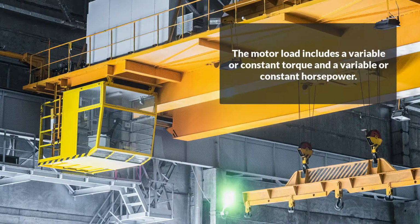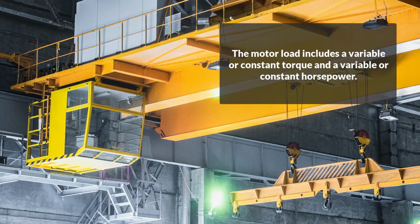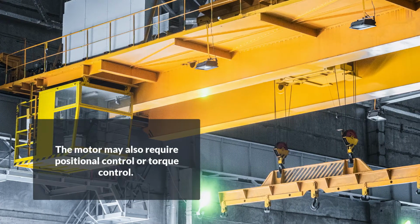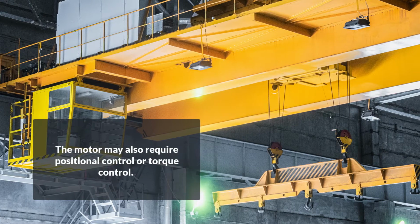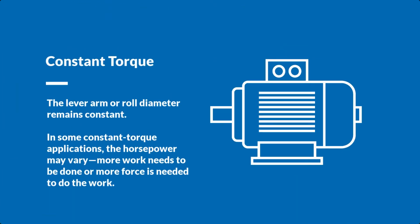The motor load includes a variable or constant torque and a variable or constant horsepower. The motor may also require positional control or torque control. Some loads are constant torque. The load doesn't change. For example, the lever arm or roll diameter remains constant.